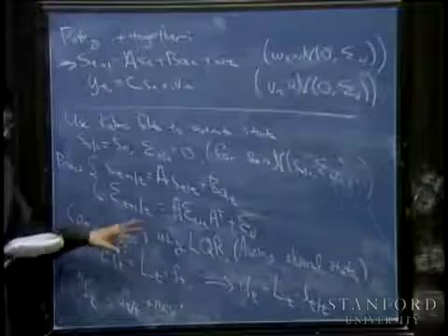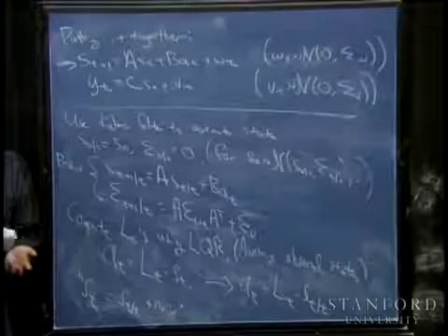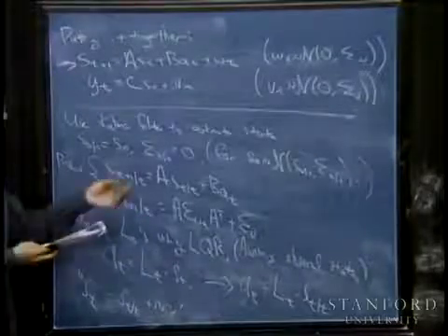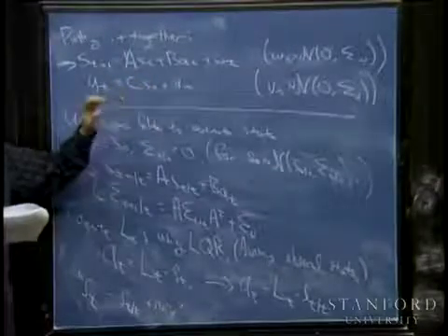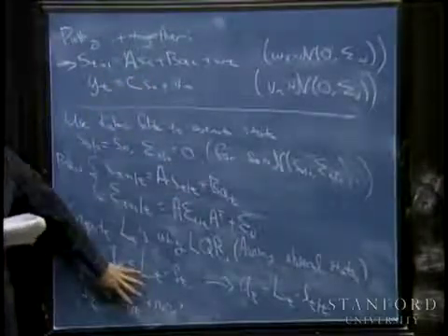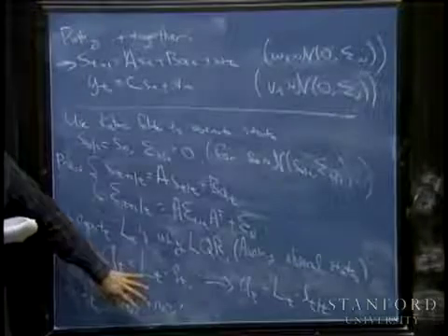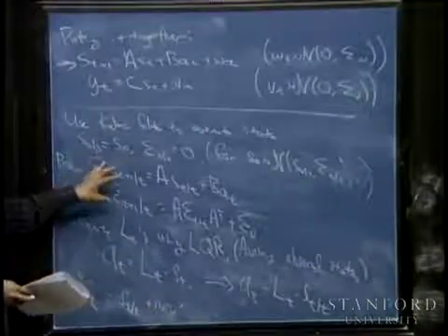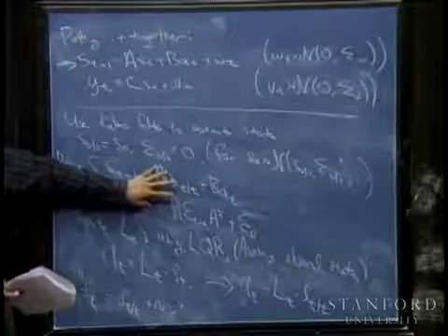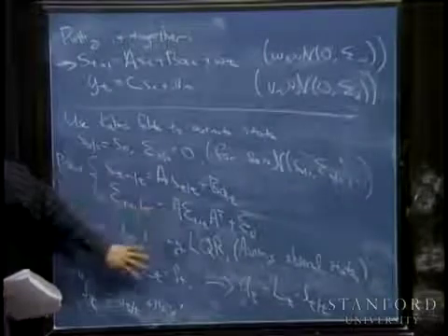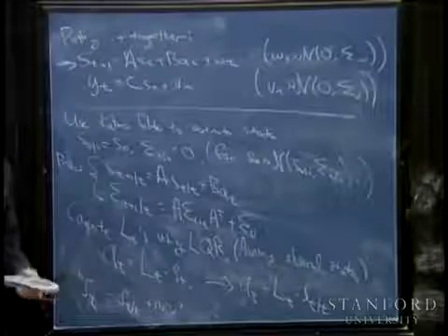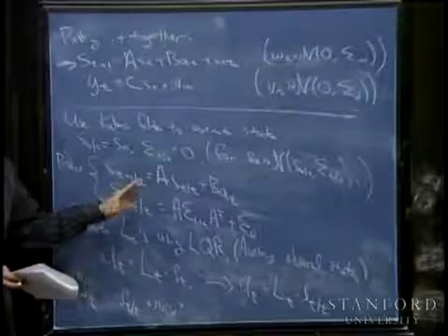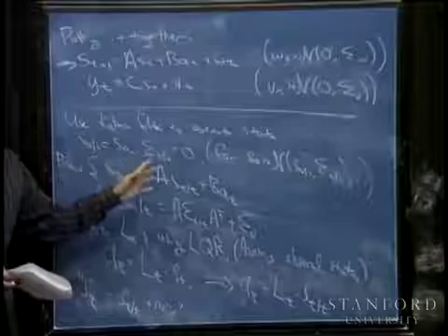I should say this is a very special case of a problem where you can ignore the noise and still act optimally. This property is called the separation principle, where you can design an algorithm to estimate the states and design an algorithm for controlling your system, and just glom the two together, and that turns out to be optimal. This is a very unusual property, and it pretty much holds true only for LQG.